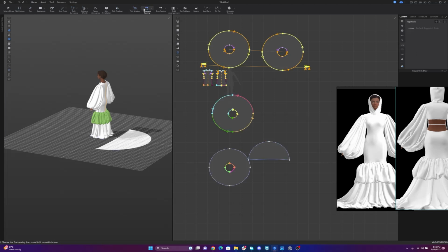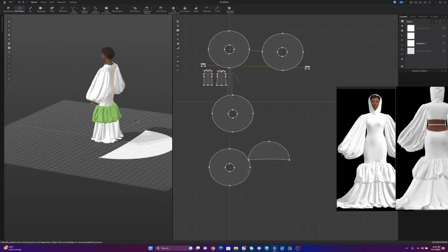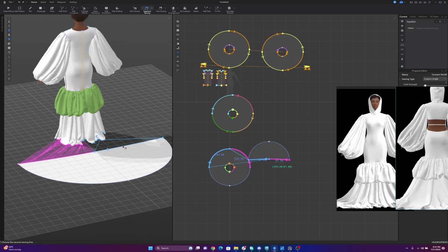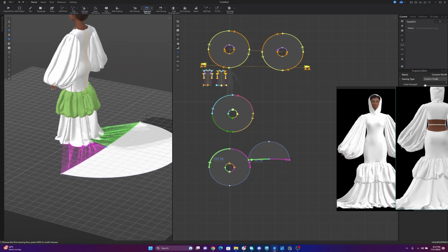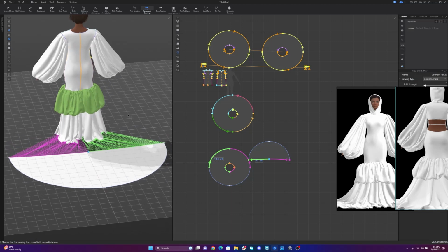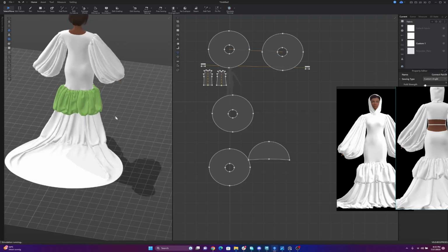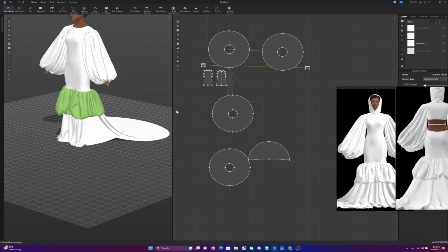Then I'm going to use my edit segment sewing to sew the part at which I want to sew together. To do that, I can mark the back part with an X and be sure this is the part I want to sew together, or create an X here for proper assurance. Use your segment sewing tool to sew this edge and this edge together, and this edge and this edge together. So you have to be sure the sewing is correct, then right click. Even if you're not sure, you are going to be sure after the sewing. So something like this is what we're looking for.